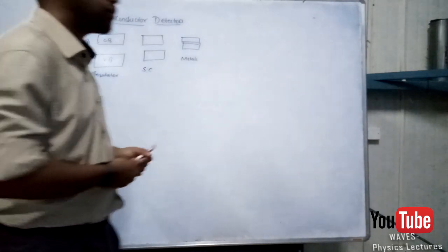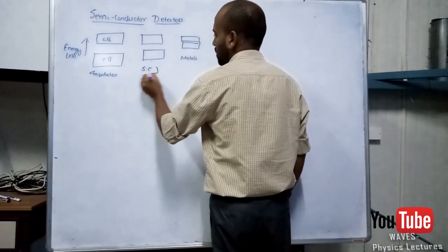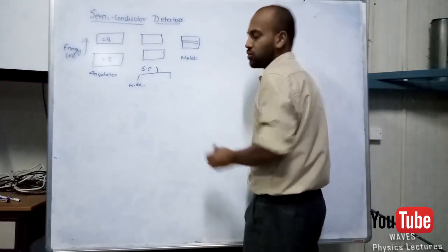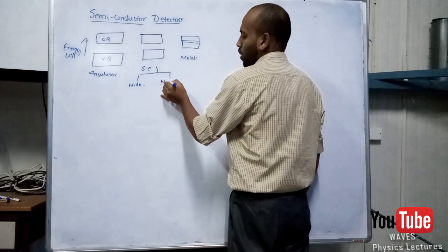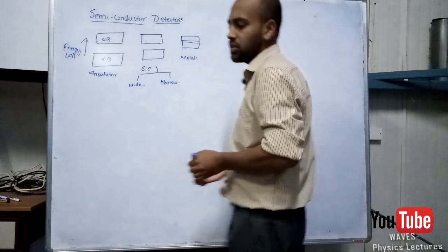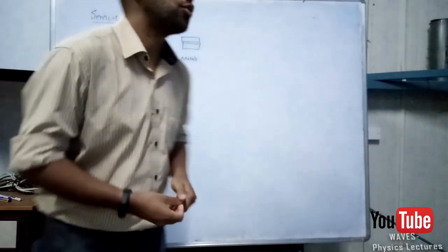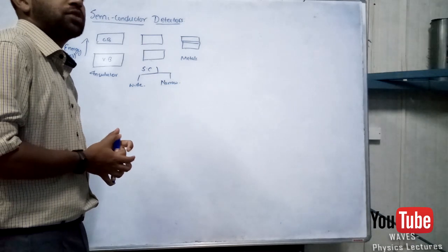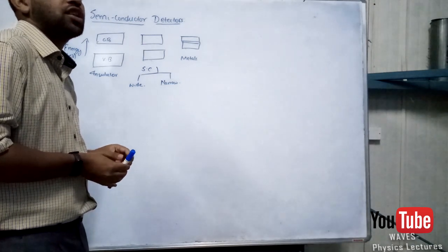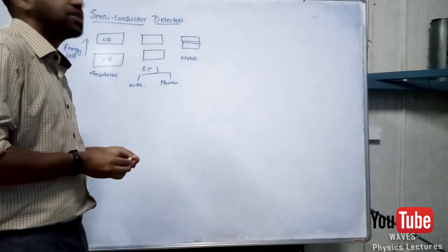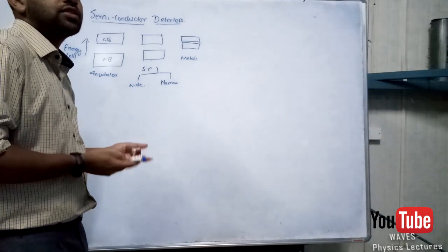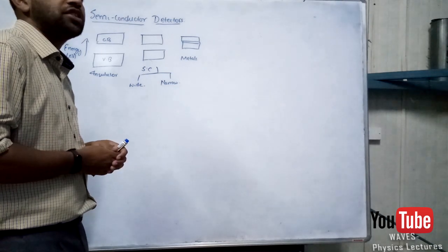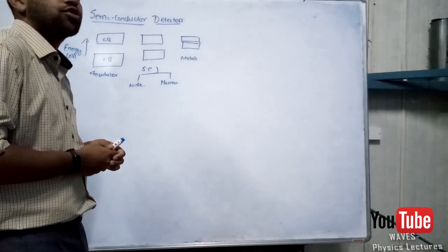If we differentiate semiconductors, these also have wide bandgap ones, right? So there is wide and narrow. Wide bandgap semiconductors, you can say anything above 2 electron volt or 2.5 electron volt, basically come into that category. Even if you consider tin oxide or zinc oxide, their band gap is greater than 3.5, which is quite a lot. We will see how much energy is needed to create an electron hole pair.